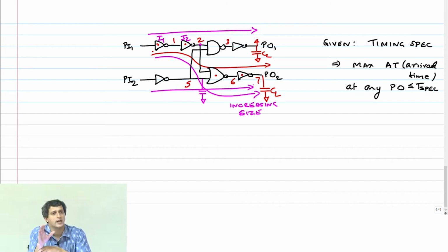And there is no guarantee that in this process of gate sizing, what we identified as a critical path initially will remain a critical path always. It can easily switch at any point. Effectively saying, you cannot do path delay based sizing on an actual circuit. Simply because I have exponential number of paths. Exponential in what? In the number of nodes.